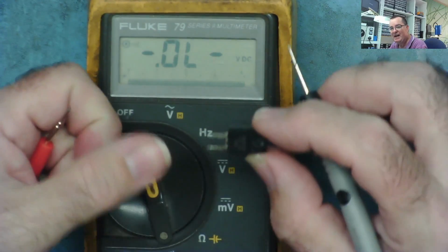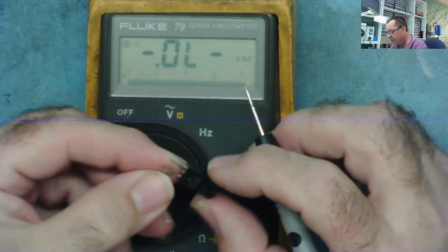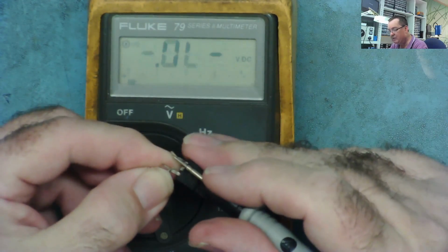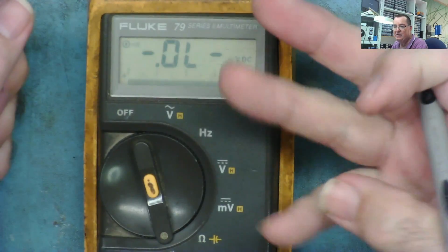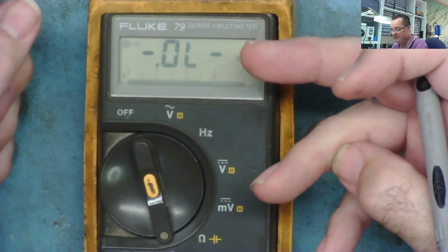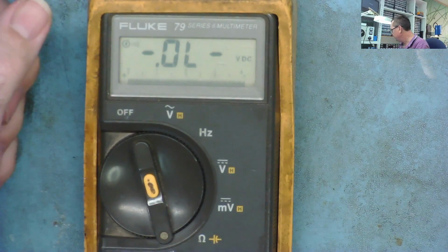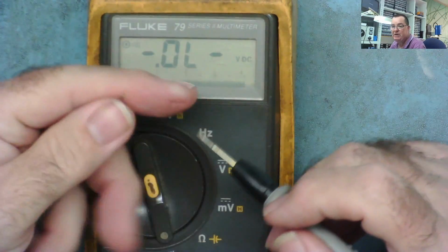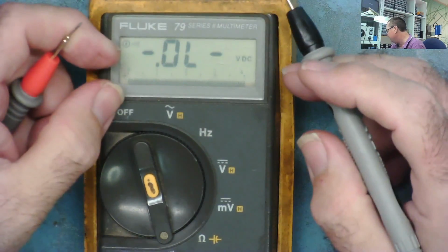A good thing you're telling now: A, you can test the diode. B, you can work out the polarity, because the anode is the one with the positive lead when it conducts. The black is the cathode, yeah? So you can figure out A, is it any good? B, is it a Schottky or a silicon diode? And C, which terminal is which? And you can work all that out with your multimeter. Otherwise, use a components analyzer. But this is the easy way to do it.